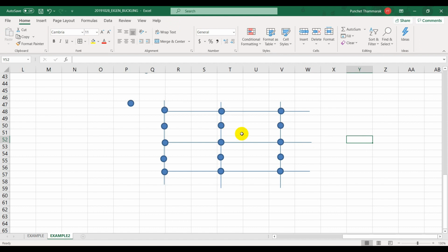Discretize and put the node at the middle of your column if you want to run second order analysis. Generally, many of you are going to use the program when you work on your thesis research. You run nonlinear time history, you try to capture the nonlinearity, and you say that you turn on the second order effect in the analysis program.